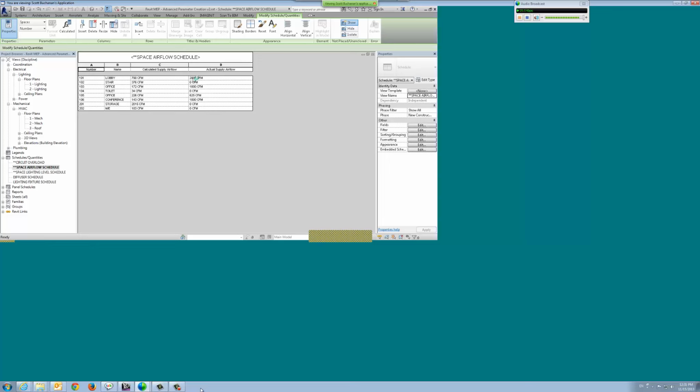So I've got these two values here. Just a quick check. I look down through here and see, okay, I've got calculated 790, I have 2,000 in there. Something's going on there. Of course, a lot of zeros just means I don't have diffusers. Calculated supply airflow 143, and I've got 1,000 in there. So nothing really stands out at me, though. I've got to look at each of these columns inside of here.